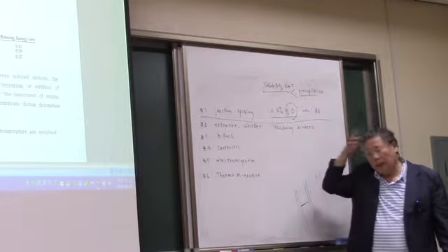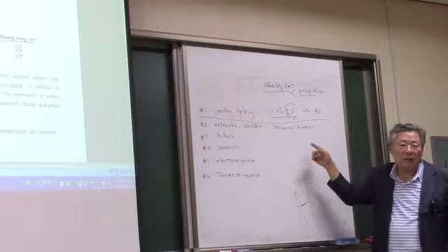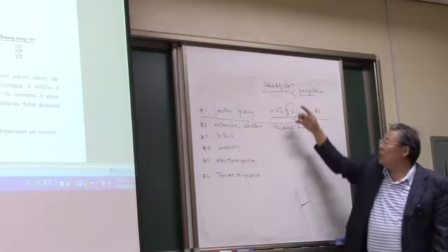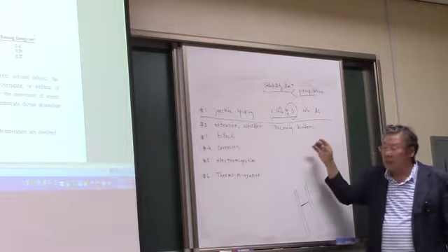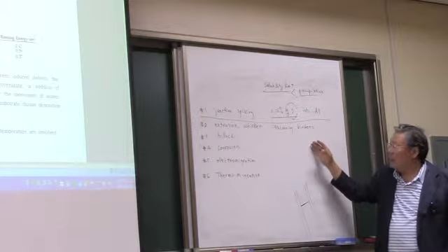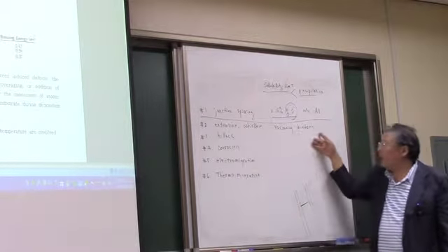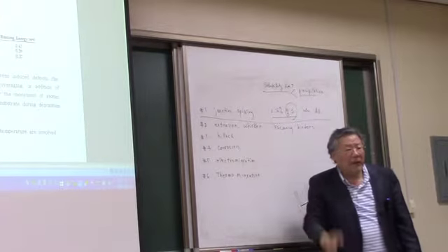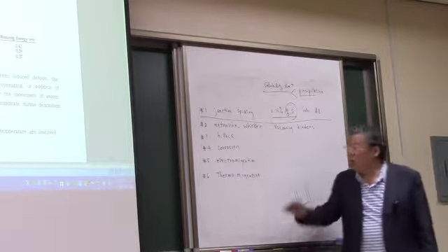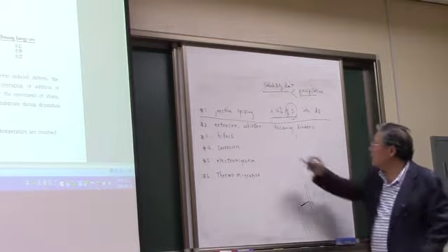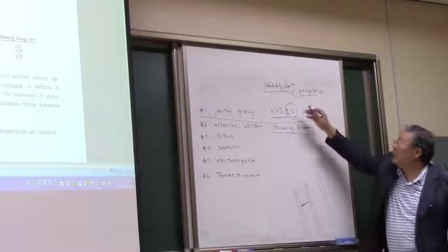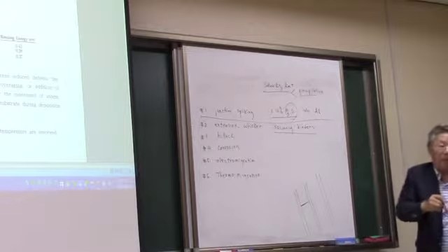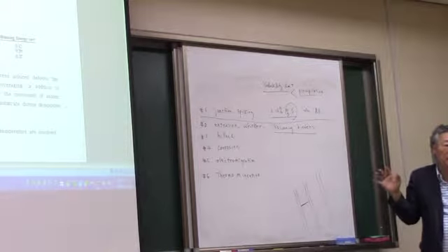Likewise, if you add the vacancy binders beyond the solubility limit in the silicon and the aluminum, then these vacancy binders will not work as vacancy binders. So we have to add these vacancy binders less than the amount for the solubility limit. Okay?